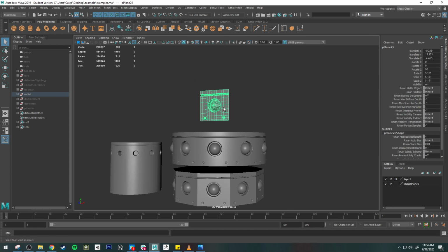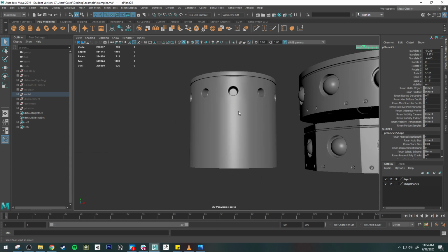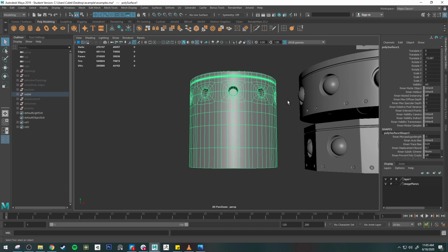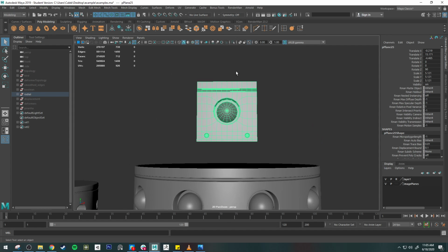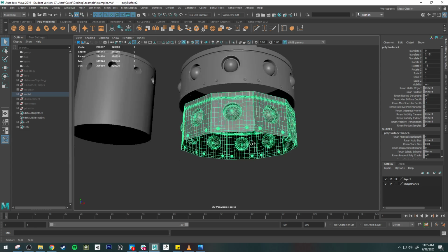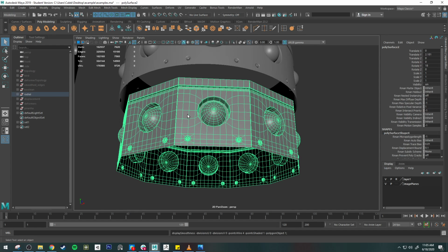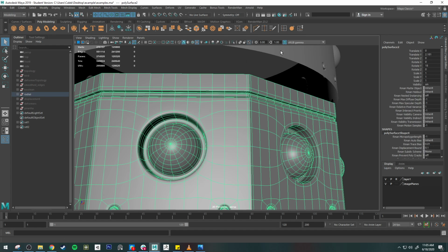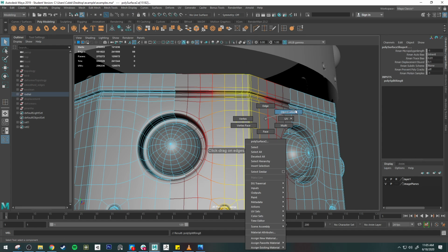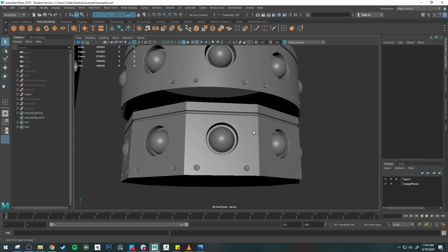This one right here, I'll go ahead and do this example for the polyhedral radial object. This one's pretty easy. I don't really have to worry about the spacing of the edges in this case, because flat surfaces aren't really affected by the spacing of the edge loops as much, right? Even though the spacing in this one's pretty consistent, even if it was inconsistent, because it's a flat object, you wouldn't really notice it that much. I could probably add an edge loop right here, and it's really not going to show up at all, because this is not a curved surface.